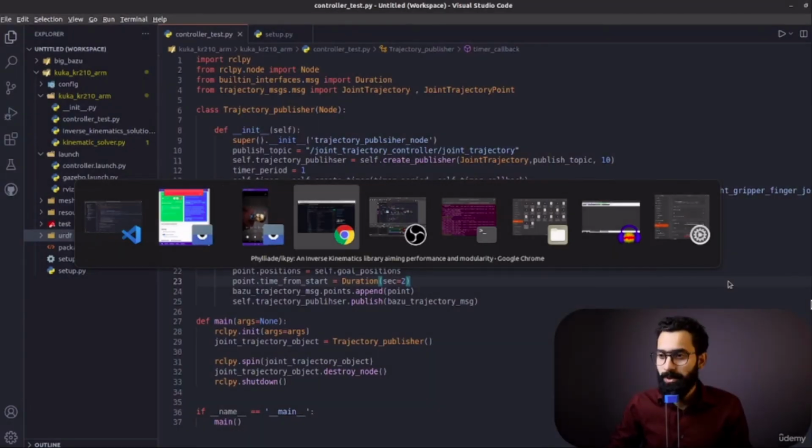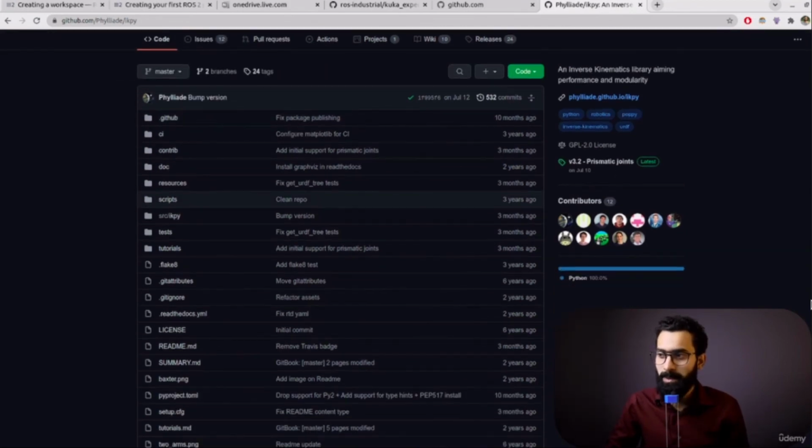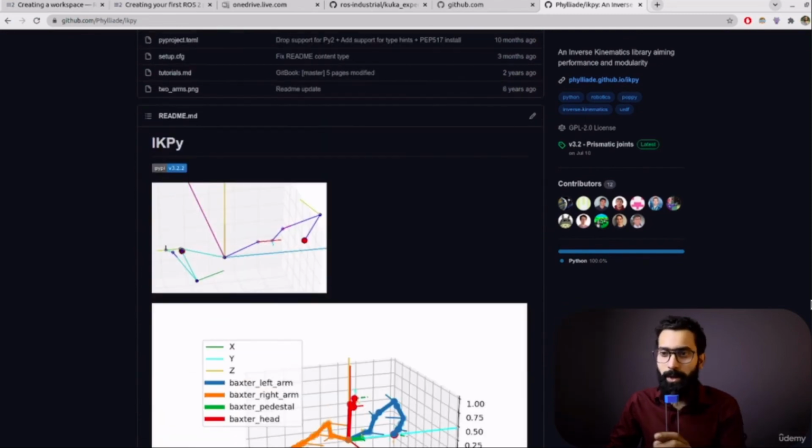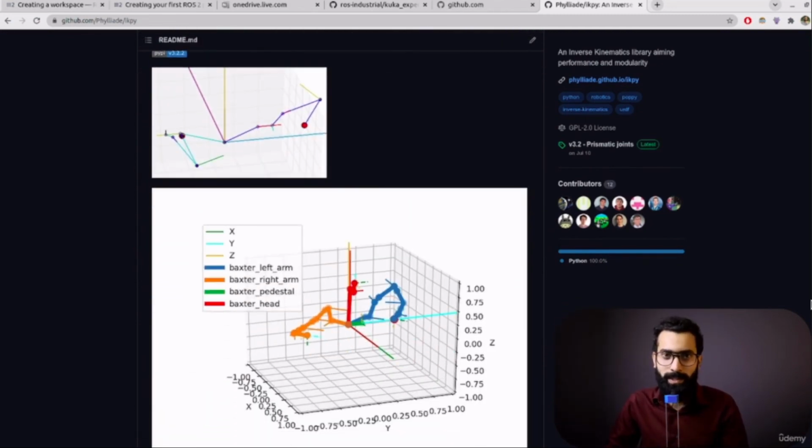Let's jump into our robotic arm and see how it looks. The library I'm going to be using is IKPy, inverse kinematics by Philippe Felt, an awesome person who maintained it and has been building it with the help of contributors to this date. This library requires just the DH table or a URDF of a robot, and it can produce very accurate inverse kinematic and forward kinematic solutions.